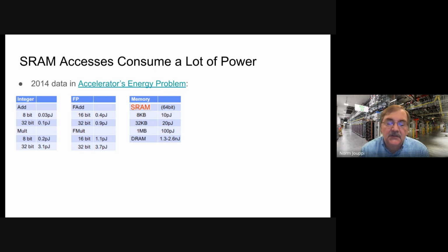One of the things that systolic arrays do is they give you great data reuse. In a 256 by 256 systolic array, you reuse the incoming data 256 times. That makes the compute the majority of the power consumption, as opposed to the SRAM or the wire.